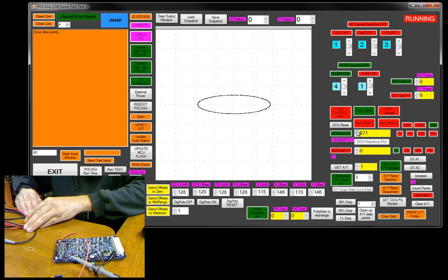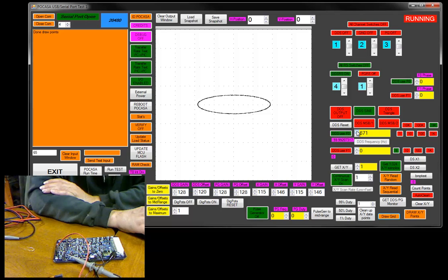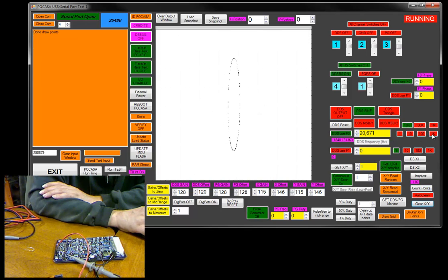So, capacitance passes AC, blocks DC. So the higher the frequency, the more the capacitor acts like a short. Therefore, when I crank up this frequency a little bit, the circle should get taller and skinnier rather than shorter and fatter. So there you go, see that? It's already at 1848 hertz, and it's a pretty good tall signature there. Now I'm going to dial this down until I get to something that looks pretty close to a circle.